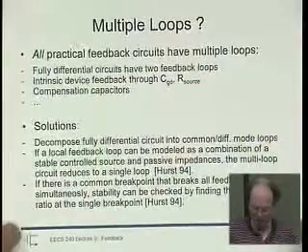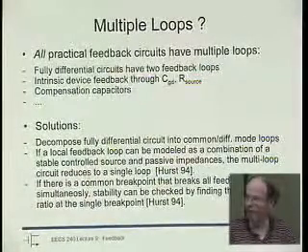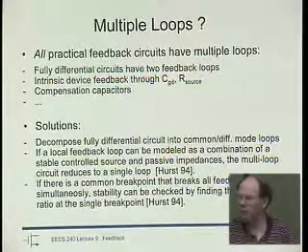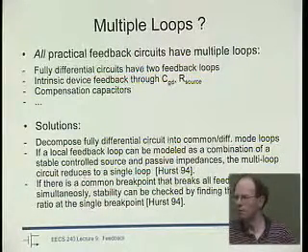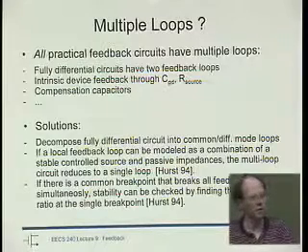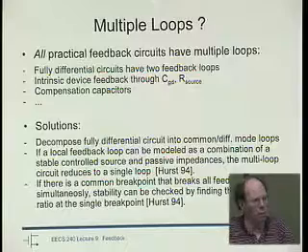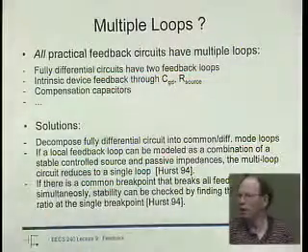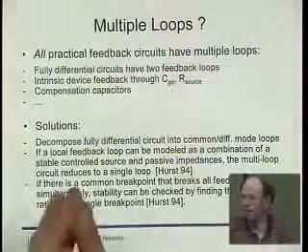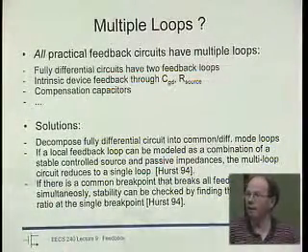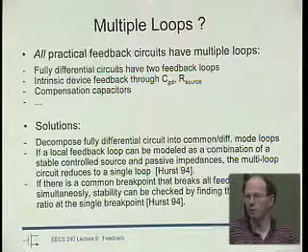Okay. So by relying on every individual amplifier or every individual transistor with its built-in feedback loop being stable, or if we have explicit feedback loops, then we test every circuit that has feedback alone, then afterwards we put the whole thing together and measure also maybe the entire feedback loop. So chances are very good that if everything was stable, then the end result was stable also. But it's not really true.